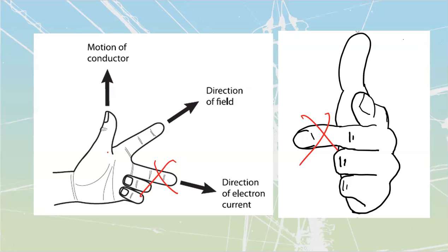After that, they go into a couple of examples. Examples 1, 2, and 3. Those examples are all worked off of Eg equals BLv. Really what they're doing is reworking that formula and isolating for different variables. In the very first one, they look at what value of voltage I'm going to generate, based upon a conductor active length that's got a field, a flux density in Teslas, and a velocity. And it generates a value of voltage.